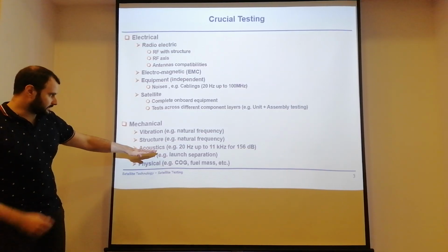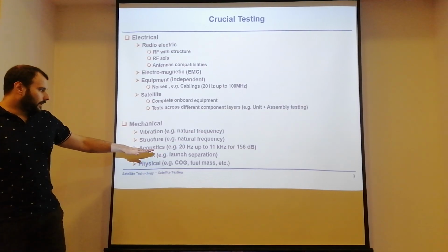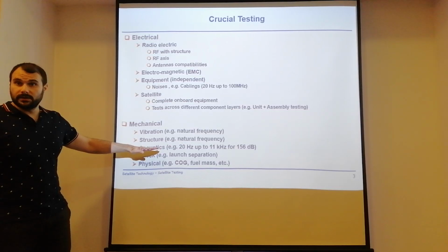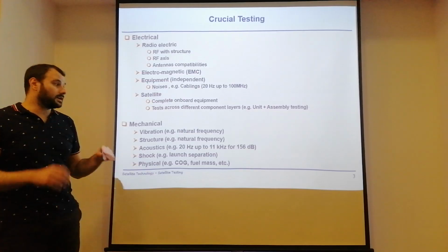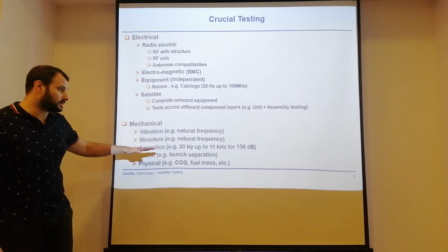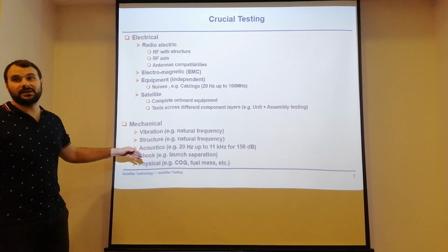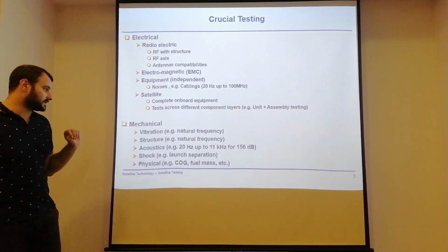You have acoustic tests because it is very loud during the rocket launch, also inside of the payload bay of your satellite. So you want to make sure that all those really loud noises don't damage the satellite. That's why you do acoustic testing.